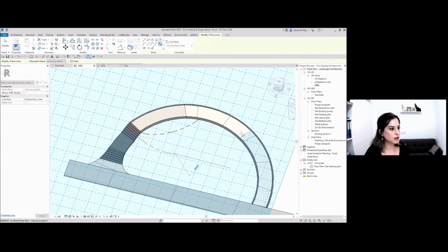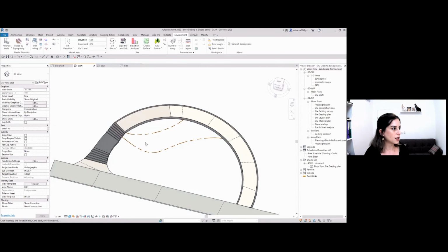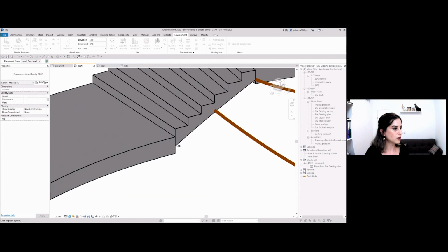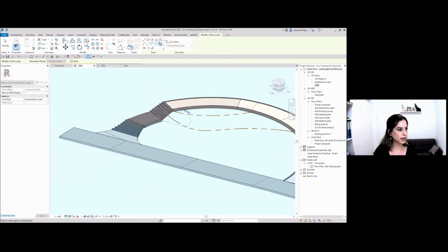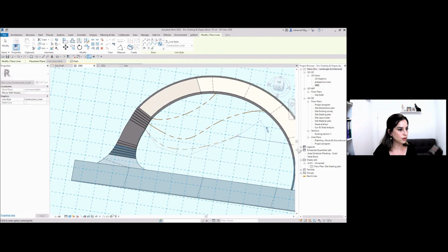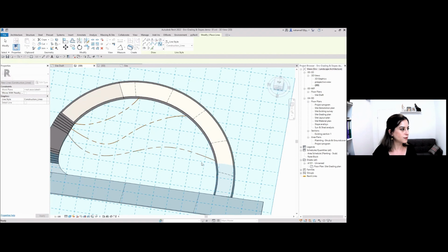And you can see that the place where my reference plane combines with my road, it's really a reference for me to understand where this contour line should connect. And then let's do it a couple more times. So one time over here, clicking, reference plane snaps to this elevation. And now I can create this beautiful contour line over here. Let's do 1, 2, 3, 4, and connect to the road.